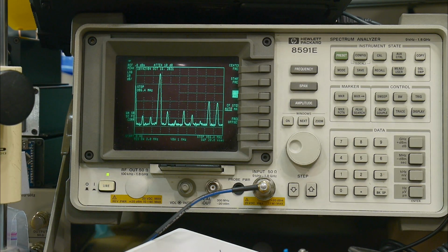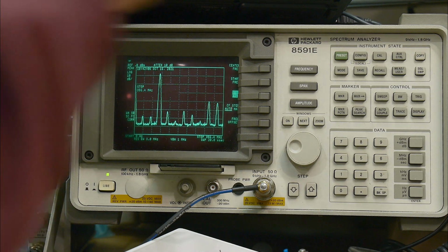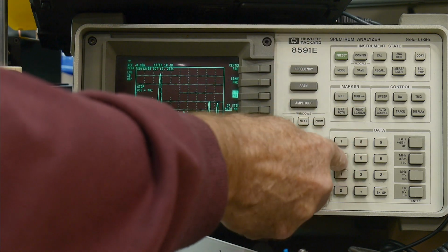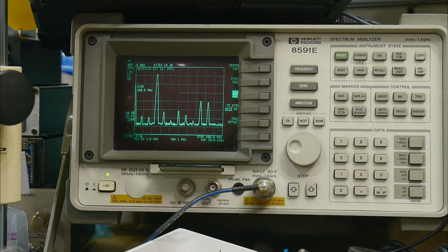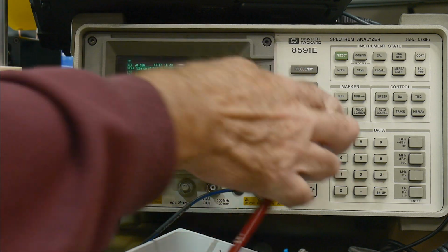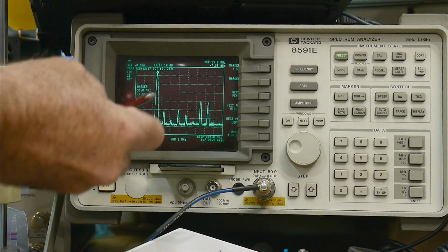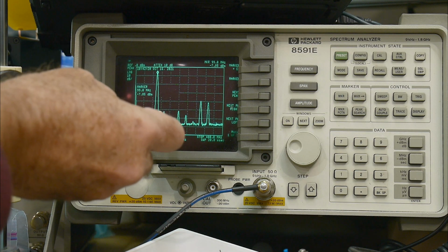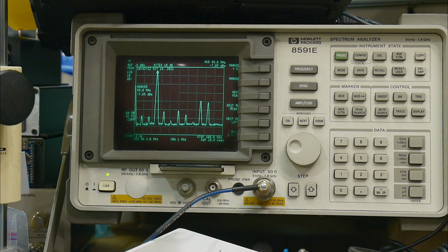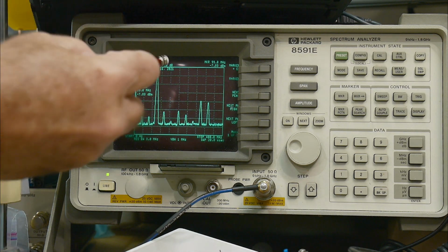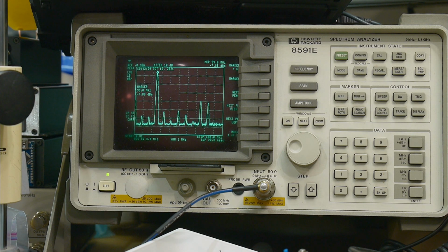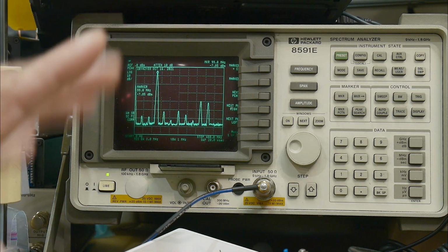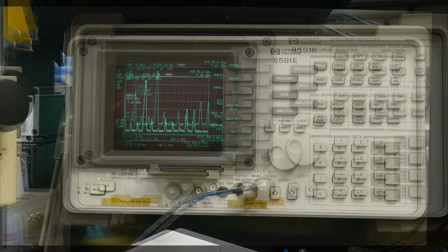Okay. So our stop frequency is, let's make it 400 megahertz. So we're going from basically DC to 400 megahertz. And if we do a peak, we see we've got our 100 megahertz carrier, and then we have some harmonics, right? But they're down 10, 20, 30 dB, something like that. So anyway, it's got harmonics, and it's got some below the carrier and some above the carrier. I did a video on that.